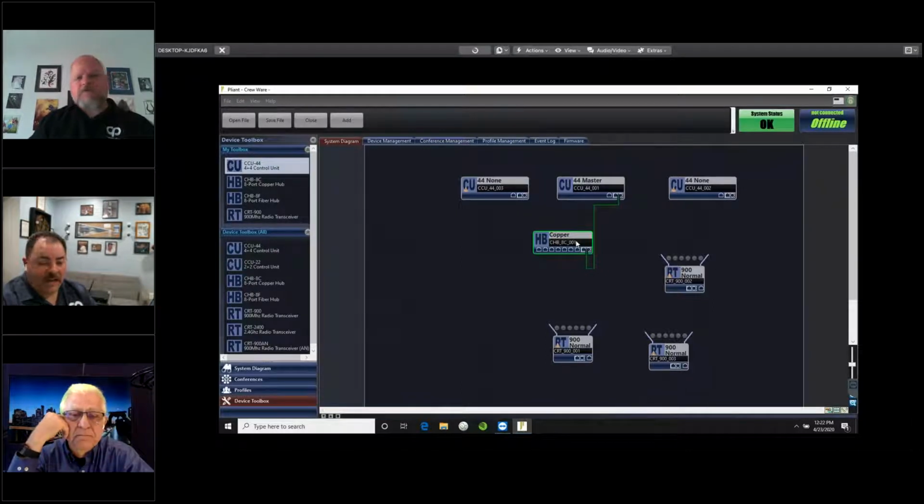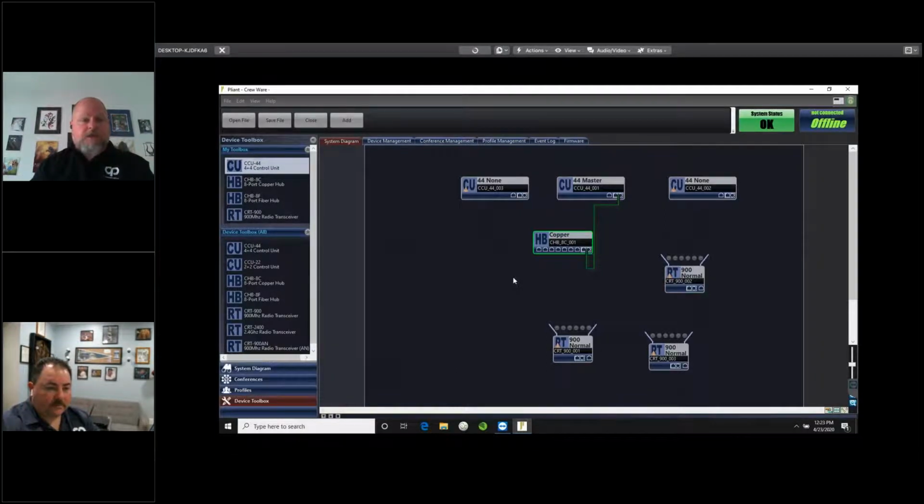Right, whatever's first in the chain. If fiber comes into the antenna, you power your first antenna, and then everything else gets PoE from that first antenna. If you're coming fiber into a fiber hub, that hub would need the local power, and then everything else would PoE off that hub. So it's whatever's the first part of the chain, then in theory you can PoE after that.